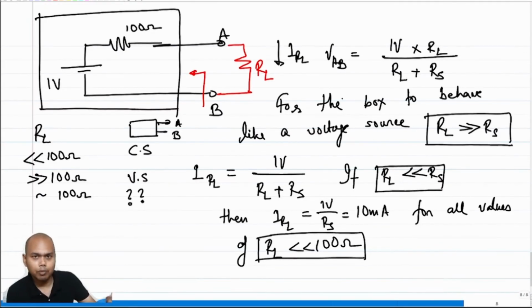So this also becomes important when you are debugging a circuit. When you are debugging a circuit and you see that your output voltage is changing when it's not supposed to change, or your current is changing when it's not supposed to change, what is the first thing that you should go and check? One of the first things is whether the Thevenin equivalent resistance at the output of your block is very high or very low, with respect to the load resistance that it is driving, depending on what you are trying to make, right?